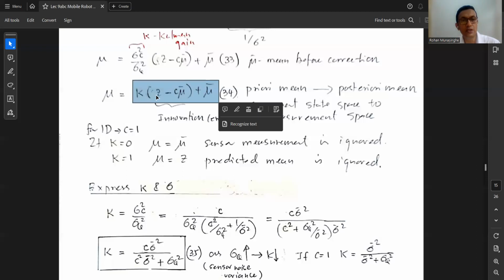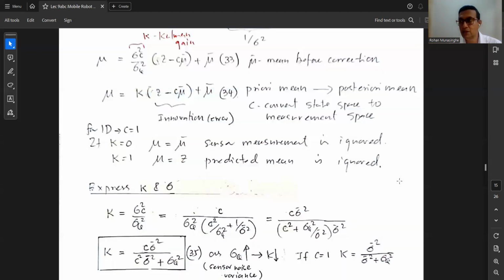You have a very good sensor, so you disregard your vehicle dynamic model and rely on the sensor, right? If your vehicle dynamic model is bad, with a lot of process noise, disturbances and unmodeled dynamics, your state transition equation doesn't say anything significant to you. In that case, you can totally rely on your sensor. Put a sensor, read it, and use it as your position.